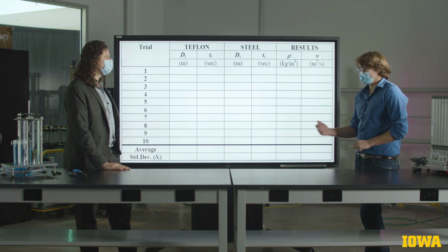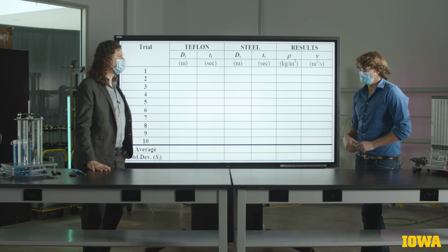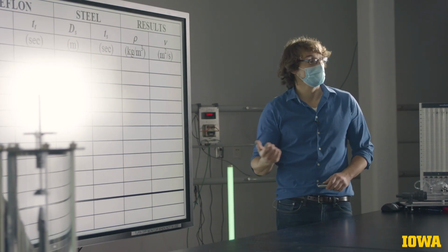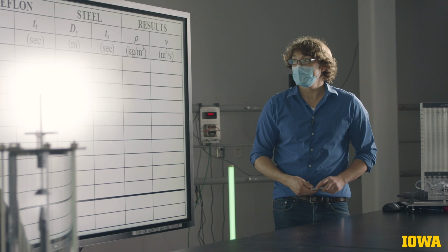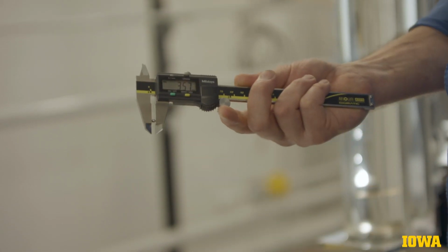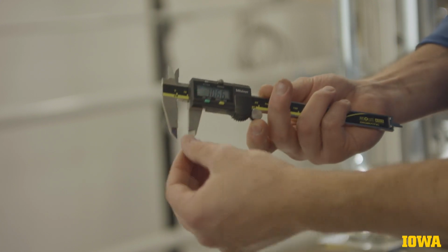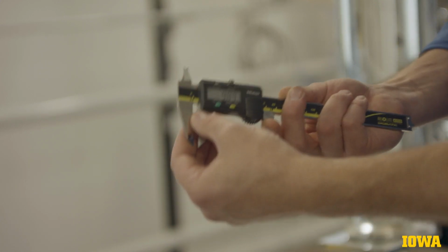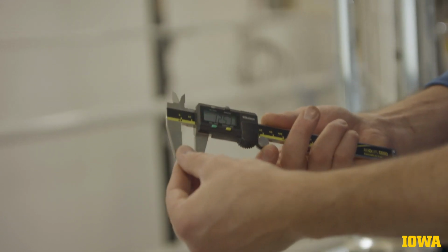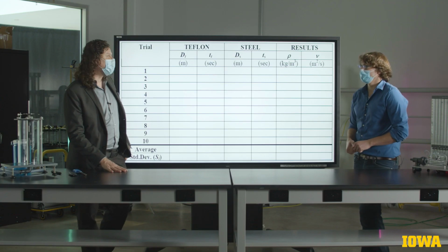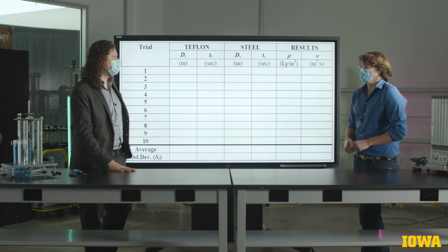Another is the timing with the stopwatch. The stopwatch itself rounds time to the nearest hundredth of a second, so there's some rounding error present in there. And we may also concern ourselves with the possible error in the measurement of the sphere diameters. We used a very, very nice set of calipers, but we saw different results each time we measured those. Yeah, so those are uncertainties that are introduced in our measurements because of the instruments themselves.